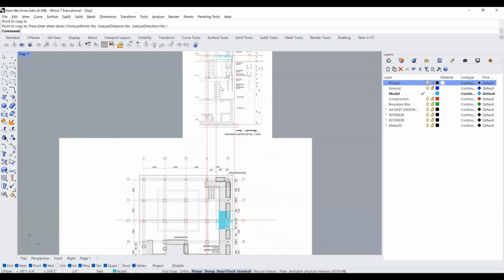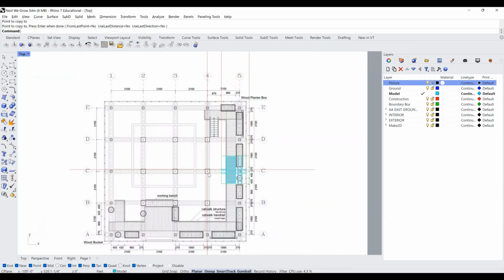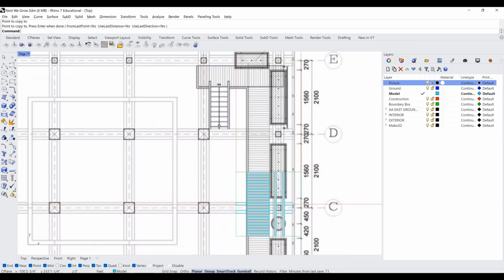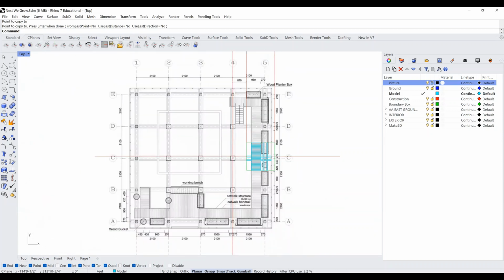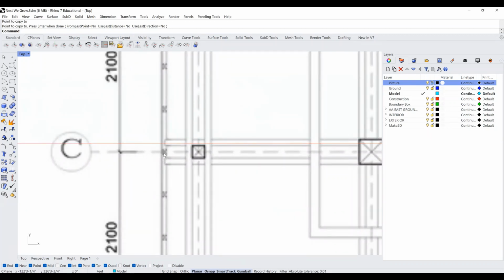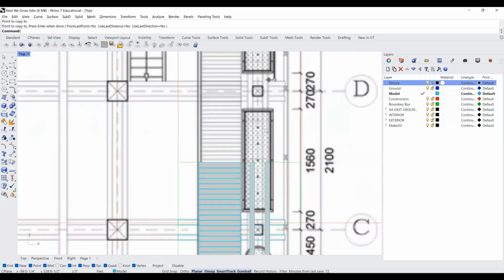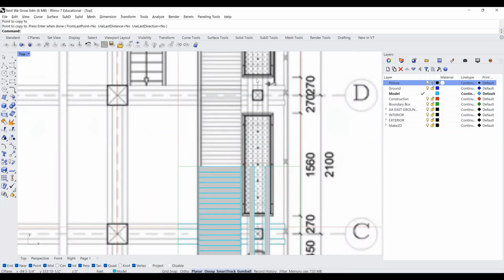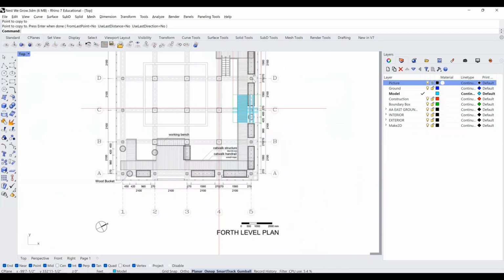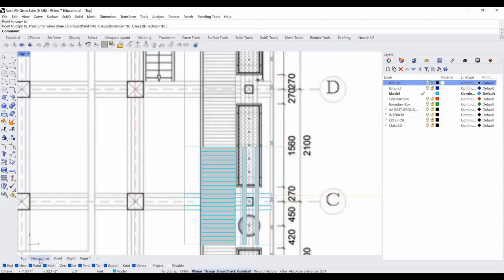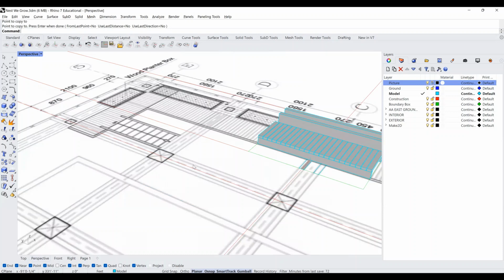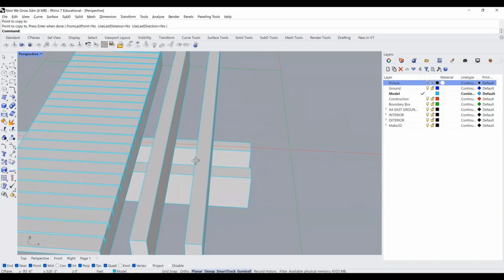So one thing that is similar to the detail drawing is that the floor plan drawing doesn't have any approaches as well. So because it doesn't have any approaches, there are these X's again that symbolize the members that are being cut. So all of these columns are being cut in this floor plan, along with these smaller framing elements that consist of the exterior wall, right? And so for now, we're going to be making this column in the middle right here within our boundary. So what I'm going to do really simply is that because I know that this column is wrapped around by these beams that go from the east-west and the north-south directions, I'm just going to make an educated guess that I can just extrude it from this intersection in here, this area right there.